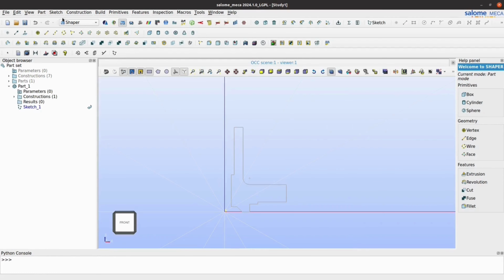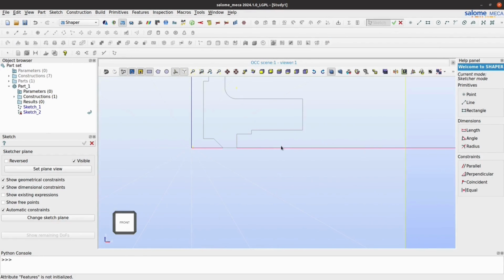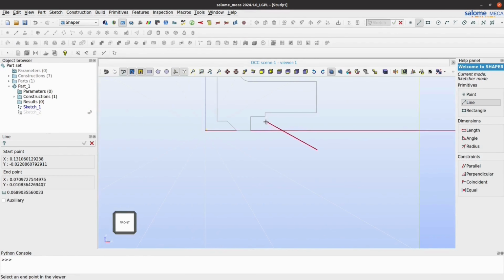Now let's go ahead and create the second sketch, which is the generatrix of the bottom part of the valve's body. Same logic here, a rough freehand drawing that will be adjusted later. You can also rely on the previous sketch for the edges where the two parts connect.